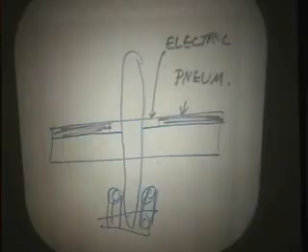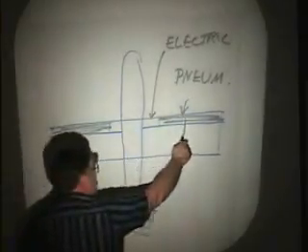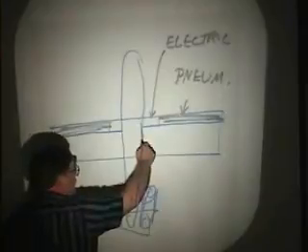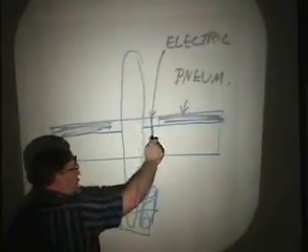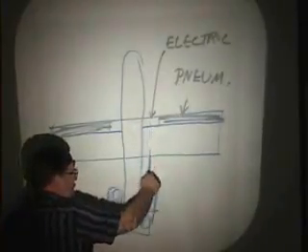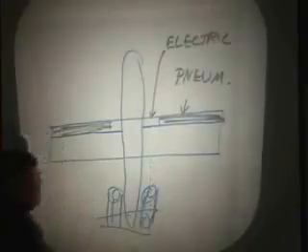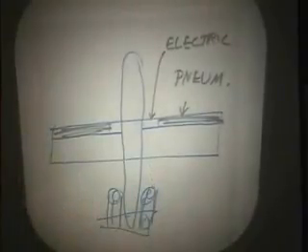Why don't they make all of it pneumatic? They don't want big chunks of ice falling into the engine. Yeah, very good, Patrick. They don't want big chunks of ice. The pneumatic system is de-ice. If we ran it all the way to the leading edge of the wing and then let the ice form and then turned it on, the ice would crack when we turned it on and get sucked into the engine, and we'd have foreign object damage on the engine.